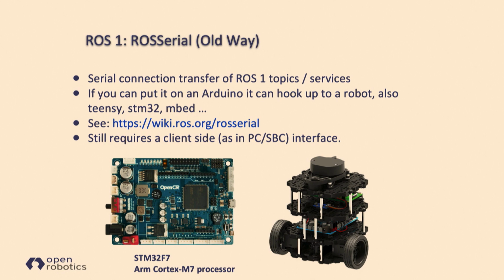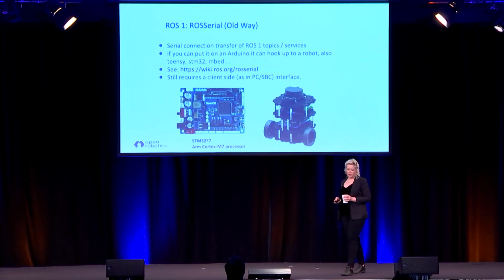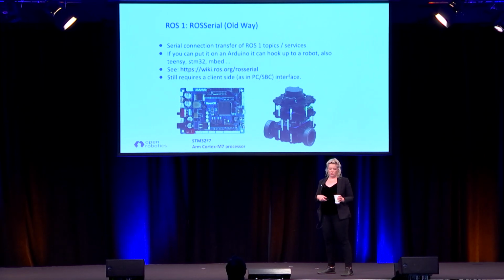This guy right here is a TurtleBot. This is our standard learning platform. It's just a Raspberry Pi with another board underneath it. This is the OpenCR board next to it. The OpenCR board is basically an ARM Cortex-M7 processor that we use as a generic board that talks with ROS to handle driving various motors and various sensors.